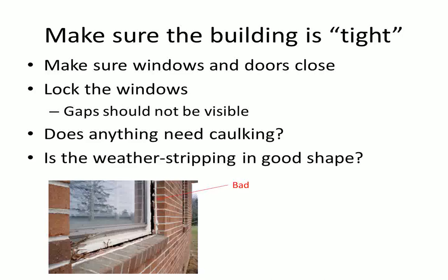Also, quick note on diffusers. These are the things in the ceiling where the cool air comes out. Do not have people sticking stuff in the diffusers in your building. That does not help at all. It actually wastes energy and makes the building more uncomfortable. The air conditioning is made to work a certain way, and when people put stuff in the diffusers, that just prevents the whole point of the air conditioning distributing the air through the building. So if you have a problem there, feel free to contact maintenance so they can come out and make some adjustments on your particular facility.